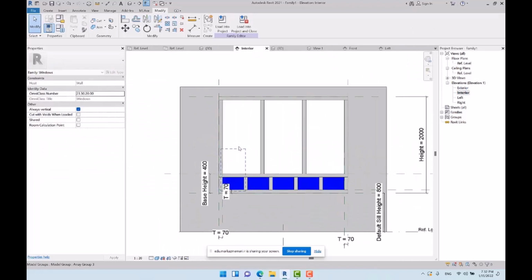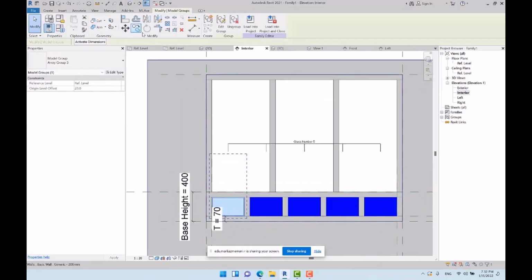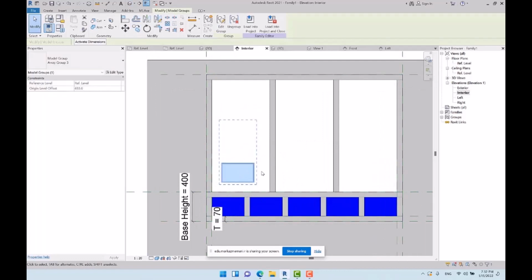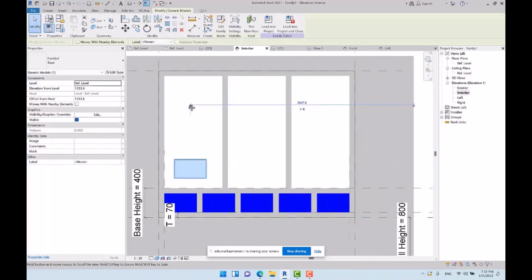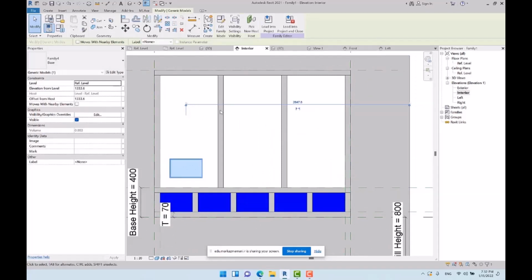I open interior view and then I select one of the glass panels. I make a copy and then I paste it here. I ungroup this part since it was arrayed, and after that I want to place the panel here on the top part, so the sides of the panel should be aligned with the profile, and we're gonna associate some parameters and some angles to create an opening inside the panel, just like a door in the 3D view, in both views of 3D and reference level plan view. And I should say that this is one of the most complicated families that you can create.